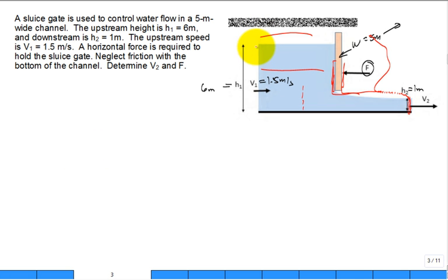And then what do I do over here? I've got to come down. Do I go deep into the ground to come across? Or do I try to go right in the water, right at the edge, and come across? What I'd like you to do is spend some time, reproduce this illustration, and give me a control volume which will work to both calculate V2 from continuity and F using linear momentum concepts.